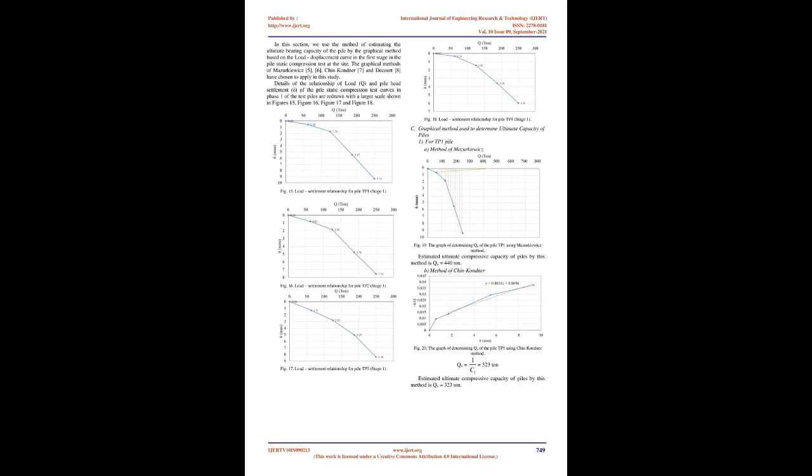The correlation between pile pressing force, Fp, and depth of embedment Z for each pile is shown in Figure 7. With each pile we found that the pile pressing force tends to increase proportionally to the pile tip depth and reaches the maximum value of Fp max equals 503.2 tons when the pile is stopped.